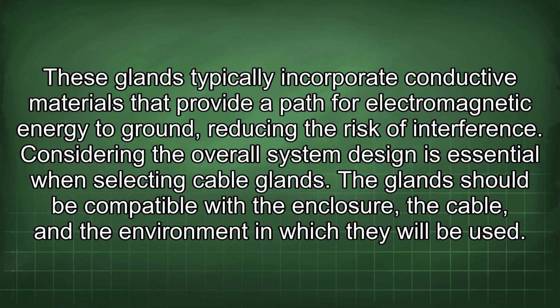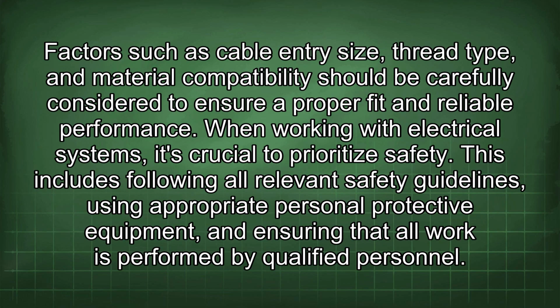The glands should be compatible with the enclosure, the cable, and the environment in which they will be used. Factors such as cable entry size, thread type, and material compatibility should be carefully considered to ensure a proper fit and reliable performance. When working with electrical systems, it's crucial to prioritize safety.